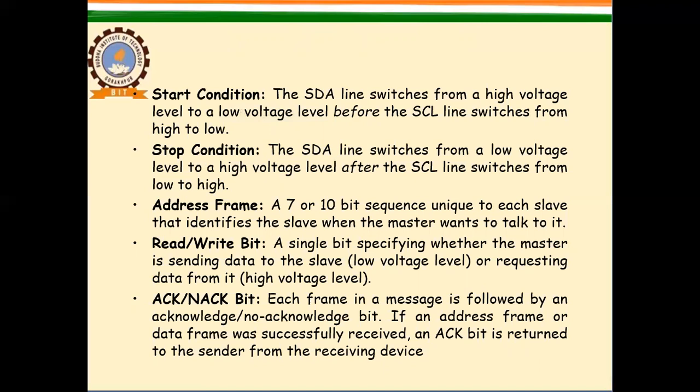The stop condition is the reverse of the start condition, which only indicates that now the whole operation is going to be terminated. The operation, which is to either read or write something in the slave, is over, and now the operation is going to be terminated. So this bit is used for that. That is the stop condition.